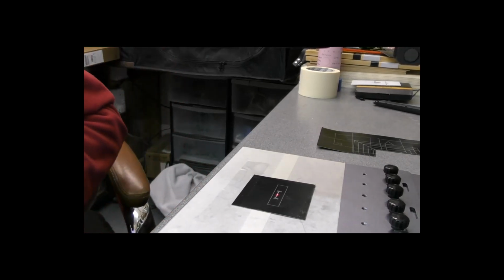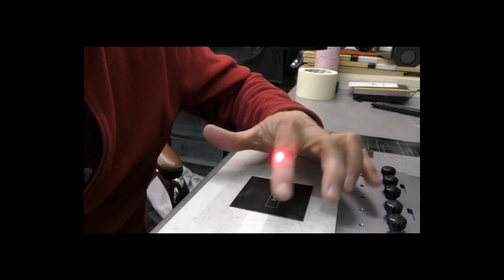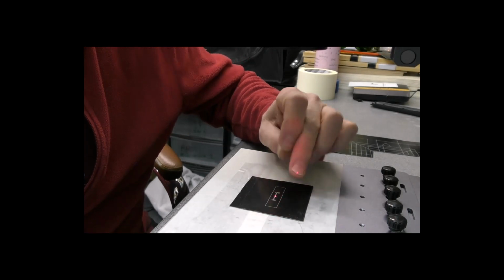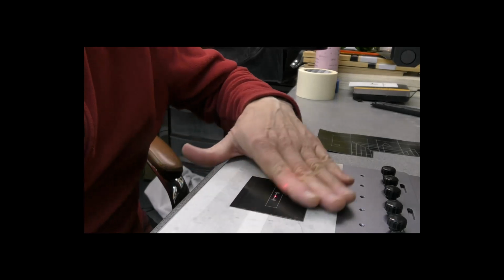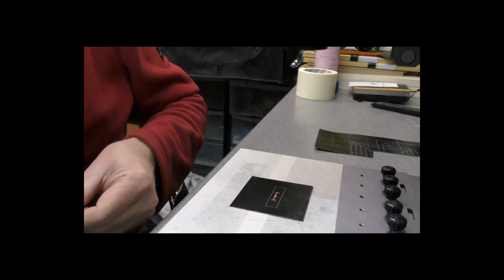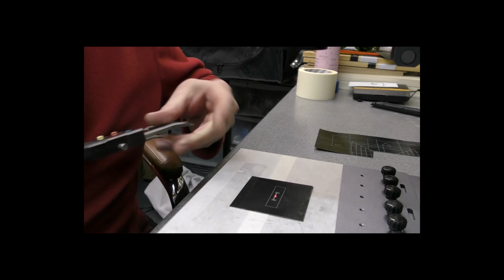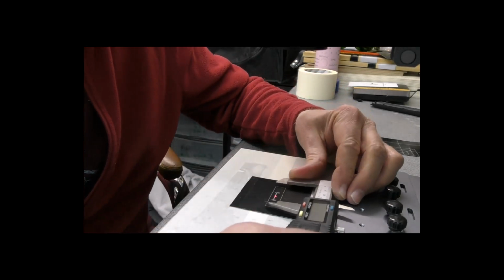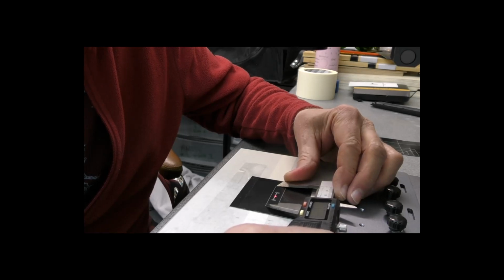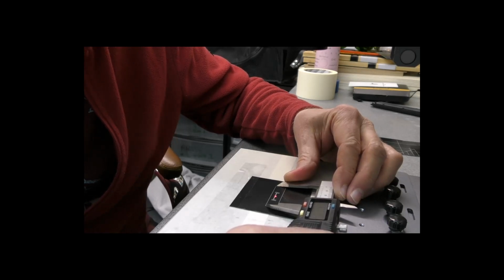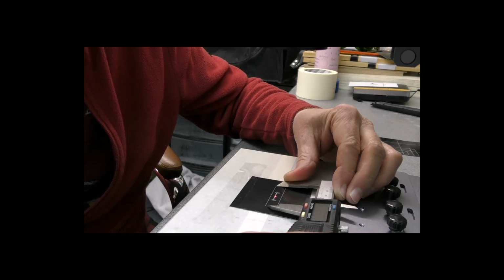Okay, so hopefully you can see that. What we have is a rectangle burnt in. We've got two capital H's and a series of dashes in between the two H's, and this was unfilled text. Now the size of the rectangle should be 40 by 10. So we're just going to grab the calipers and I would say that is absolutely spot on, as good as I can measure. 39.95.